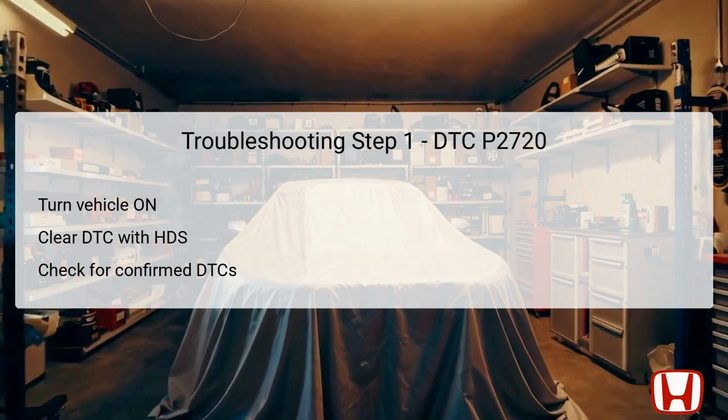or looseness. In the second troubleshooting step, begin by turning the vehicle off to ensure no current is flowing through the circuits. Following this, utilize the HDS to jump the SCS line, which allows for testing without interference from other circuits. Disconnect the PCM connector A, which has 51 pins, specifically from the vehicle to avoid any additional variables. After these preparations, turn the vehicle to on mode again.